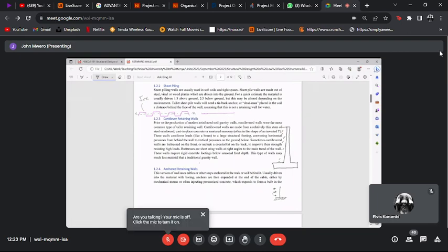Okay, this retaining wall is efficient in material, so you don't need a very thick element to get it right, but it requires, well, all retaining walls require good design. Recently, not many months ago, I sat in a panel where we were looking at a case where a retaining wall collapsed. This retaining wall was designed as a cantilever retaining wall, but the engineers involved did not design it. They just picked some design and they specified.